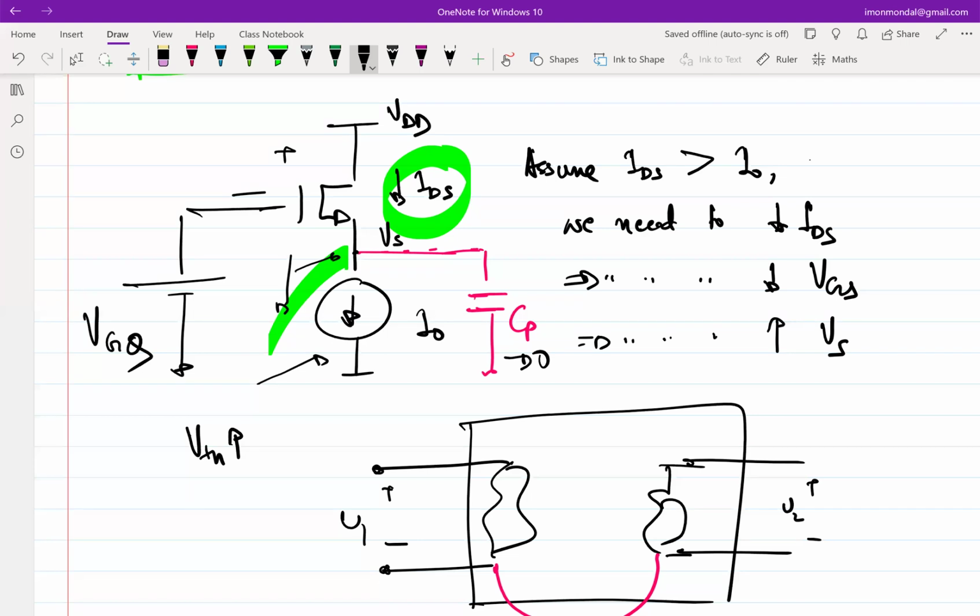So you cannot have one current source for each transistor in the network. You can have thousands of transistors, but that doesn't mean you can have thousands of current sources. There has to be one master current source, just like you have a master VDD, and derive the requisite current from it. So we have to figure out a way of getting this current.